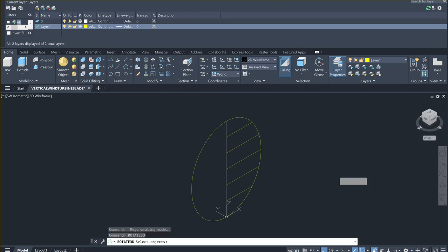3D. And it will ask you to select object. Enter. Then it will ask you what direction you want to rotate around, what axis. The axis is asking you, actually the z-axis. You want the z-axis to be pivot. So you pick the z-axis. First line, end of the first line, intersecting the z-axis. So this is my way of saying this is the z-axis, okay, that I am making reference to.